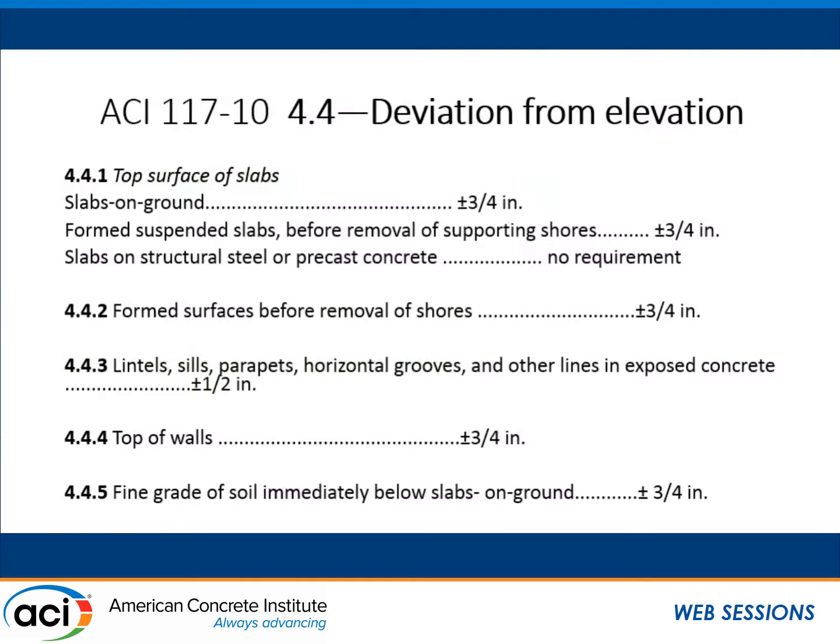Deviation from elevation. We talked about floor flatness and levelness is measured within 72 hours or a time requirement or removal of supporting shores. I'm going to call that like an operational or procedural requirement. On elevation, our elevation on suspended slabs is before removal of shores, right? So again, we've got something covered there.